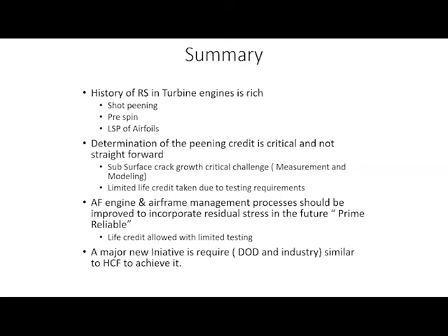And then just to summarize, the history of residual stress in turbine engines is rich. Shot peening has been around forever. Prespinning we did in the 70s and LSP of airfoils has been very successful. The determination of the peening credit is critical and not straightforward.